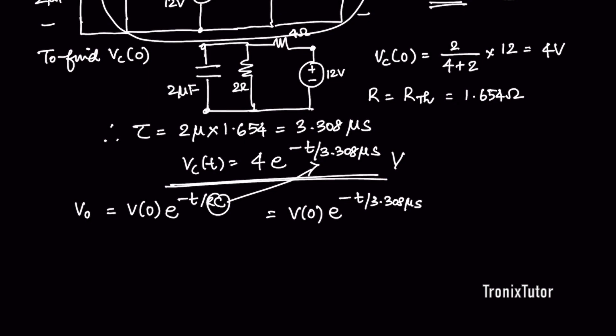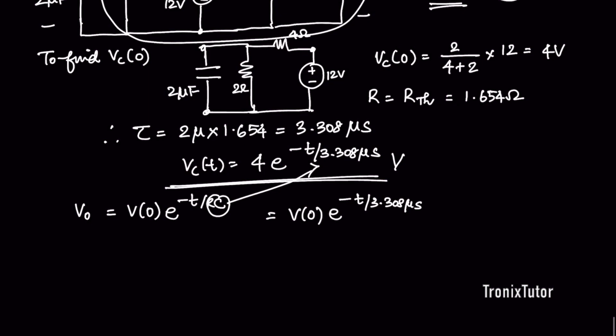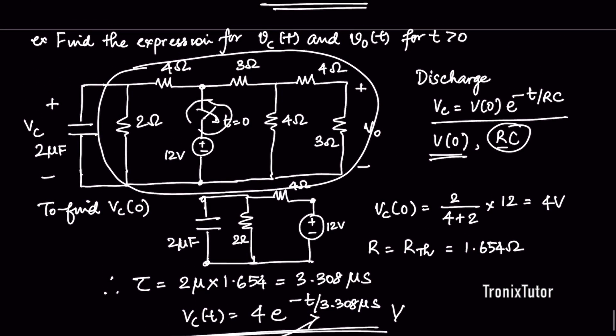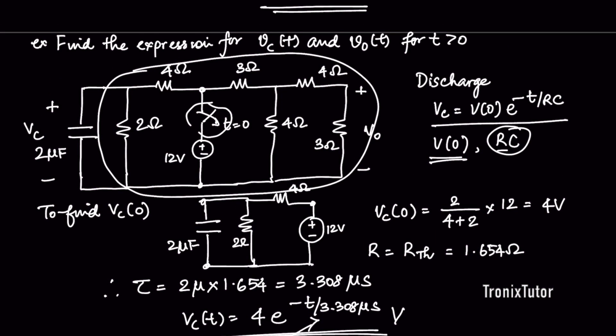So as long as I find what that value of V of 0 is, then I have essentially solved the function also for the voltage across the 3 ohm resistor. So again, in circuits like this, it's essential to first find the time constant. All other circuit parameters essentially are going to behave similar to that, either a dying exponential or a rising exponential.